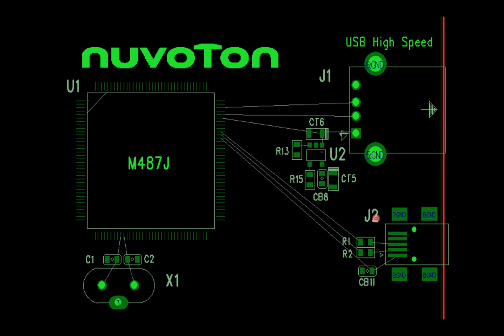And next, the USB 1 of M251 is a full-speed device port. There is only one USB connector and two damping resistors for the device port. For USB full-speed device, we place the B-type connector outside the pin 98 and 99 of M251, but it still needs a space to separate from U2, which means it has to be placed at the edge of the board underneath the U2. And then place two damping resistors near the USB connector.